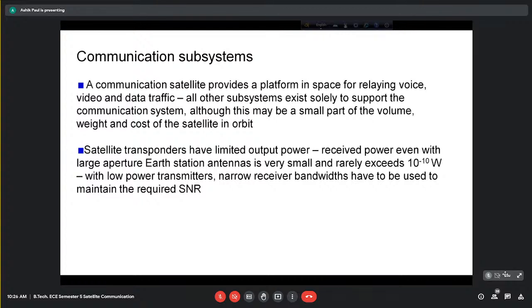And people sometimes, in Germany, went on to build one antenna which was like 100 meters in diameter. 100 meters is nearly 340 to 350 feet in diameter. A huge structure. Because from your antenna classes, I think you already know that the larger the aperture, the greater will be the gain of that particular antenna.